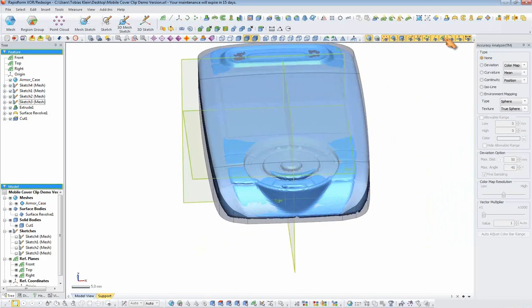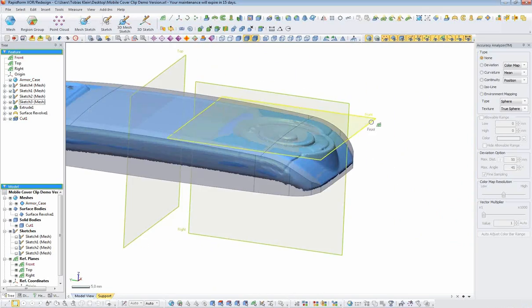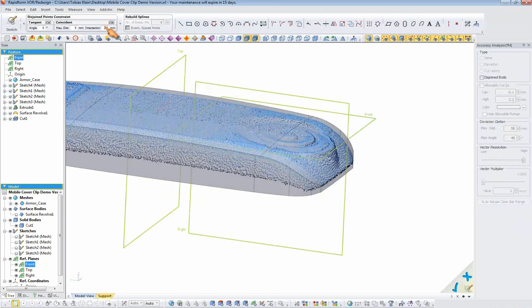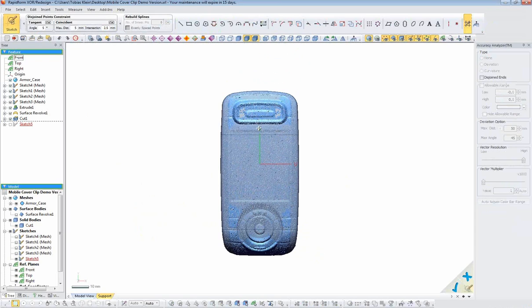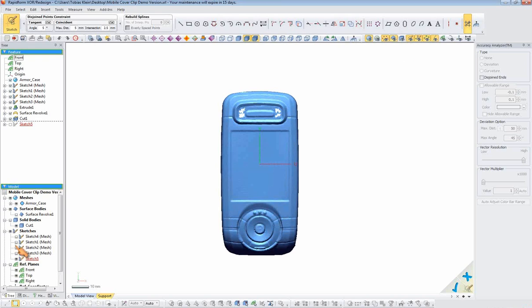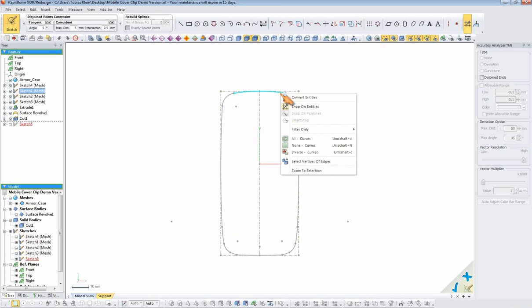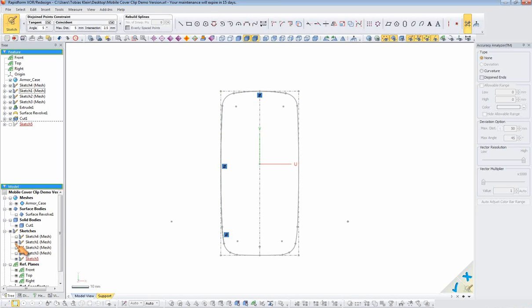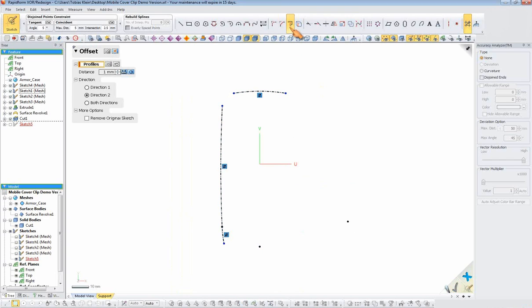I would design that character line in 2D as well, so I can use this front sketch again and just use a sketch looking from the top to that part. Let's see the first sketch which we did. That was our first sketch. So I can reuse entities which I already created. I don't need to create them again. So I can reuse the sketch and convert it, and I can get this line and convert them, and I can use them as construction geometry for the next sketch, then I can use an offset.